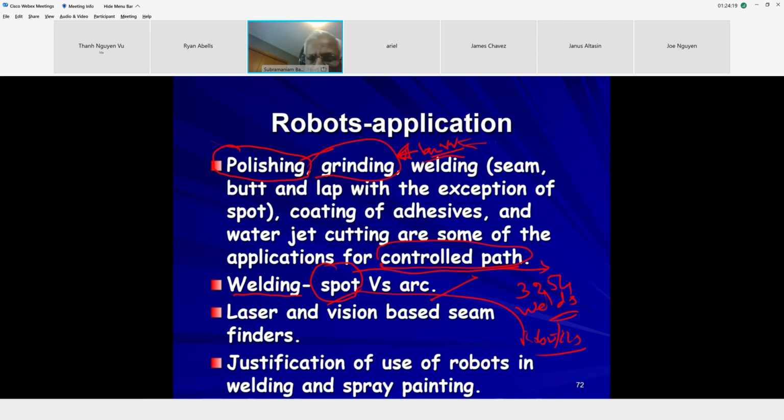So they donated most of the robots to universities and said, you guys figure out what this problem is. So many universities in the United States benefited. Everything was brought back and the robot was made to do those spot welds more reliably. Spot welding requires point-to-point, PTP, because you take the gun, hold, and lock onto a spot, boom, you're done. Whereas an arc is a different beast. The example I would give is welding the seam of a pressure vessel.